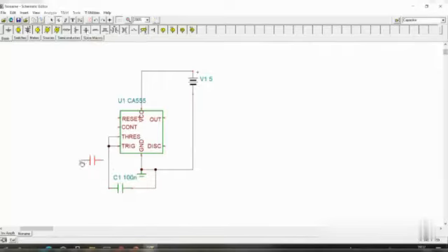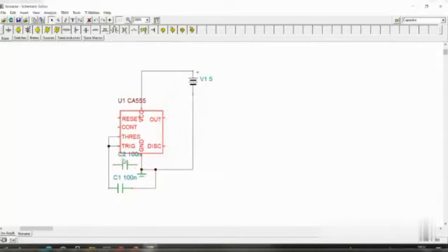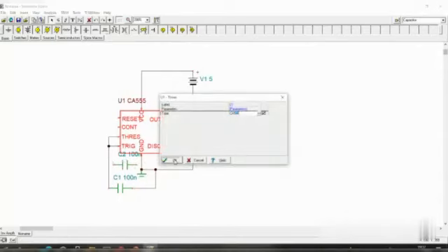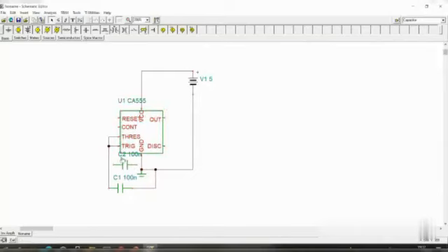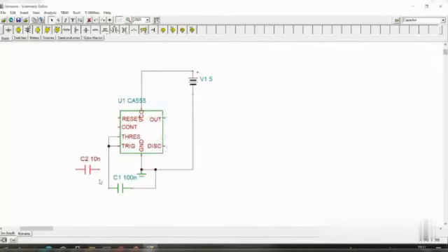Okay, and that capacitor, maybe you can put it here itself, no problem, because the other end of the capacitor will be ground. Here this capacitor is not 100 nano, it should be 0.01. This is selected as 555 now. So this capacitor, what we will do is just change the capacitor. You can select the capacitor, move it to the outside, then select here, then make it 10 nano. 10 nano is more than enough, even 1 nano is okay.